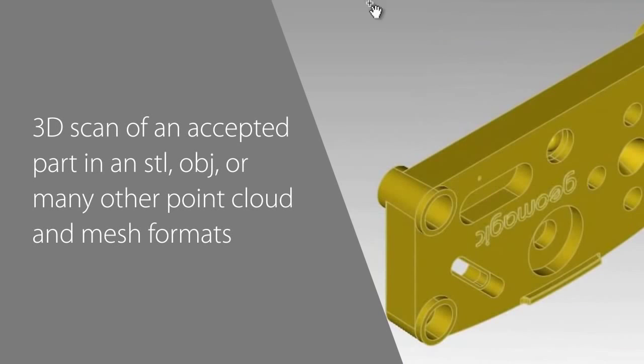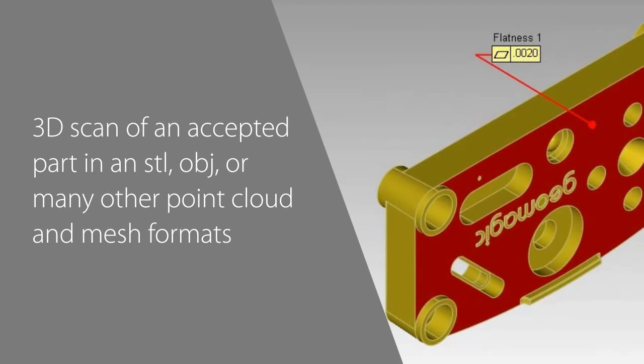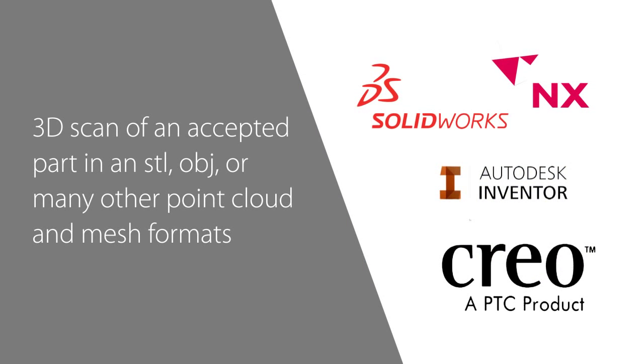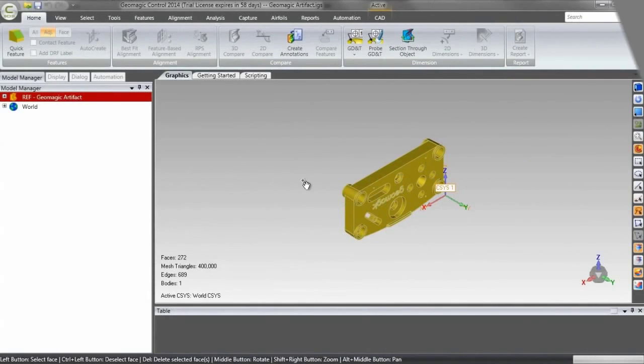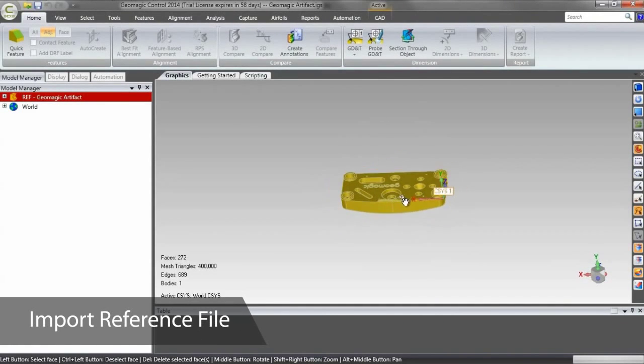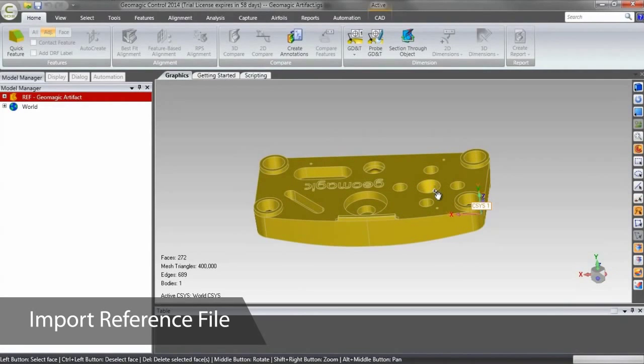The first step in setting up our automated inspection is opening a reference file. This can be a 3D scan of an accepted part in an STL, OBJ, or many other point cloud and mesh formats, or a body created in a program like SOLIDWORKS, CATIA, Creo, ProE, or Inventor. Control will open up files from those programs natively, or generic CAD formats like IGES and STEP, as is the case with the reference file here. Because this is a CAD body, Control assumes it's the reference object all scans will be compared to.